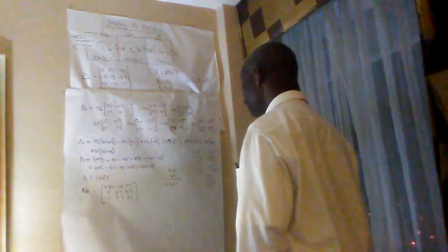And so we say now that I1 will be equal to, we replace the first column by the voltage values and find the determinant. So that will be 480, 0, 0, 0.9, 0.3, 0, 0, minus 0.3, 10.